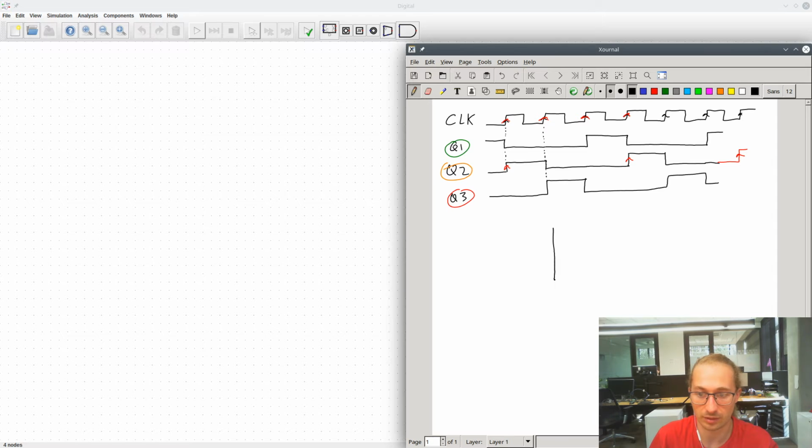So we need some sort of binary counter, which will be implemented as 2 flip-flops, because each flip-flop stores 1 bit. So here are my 2 flip-flops. D and Q are the inputs and the outputs, and they share a clock line, so they will get updated synchronously. There we go. So I have 2 bits here. We'll call this maybe state 0 and state 1.